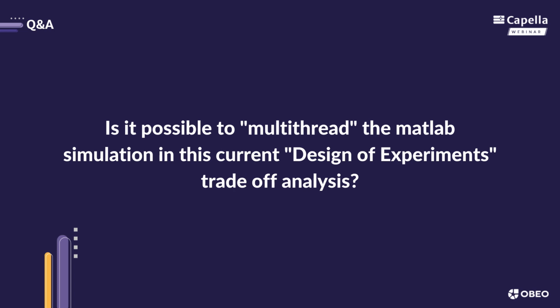Okay, is it possible to parallelize the MATLAB simulation in the current design of experiments trade-off? Yeah, and you might want to say something too, Alex, but it's not really multi-threading, but we can set up ModelCenter so that it will take multiple MATLAB simulations and run them in parallel. So that is possible, yes. Yes, indeed.